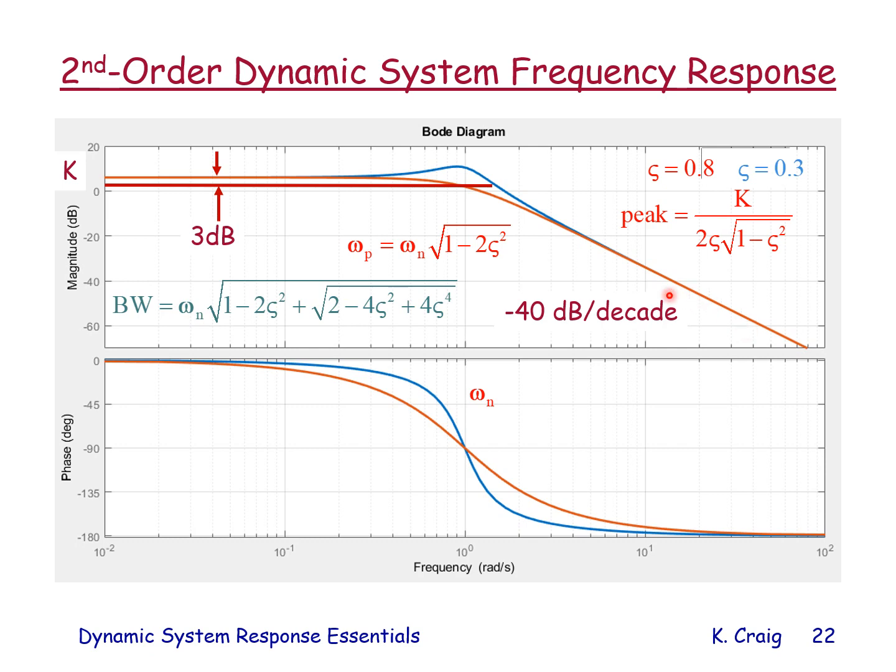A couple of points to mention. When the frequency is omega n, all of the curves here in the phase plot go through minus 90 degrees. So to identify where minus 90 degrees is, or when the output lags the input by 90 degrees, look at the frequency at omega n. And so you can see how the curves are different, but they all go through that point.